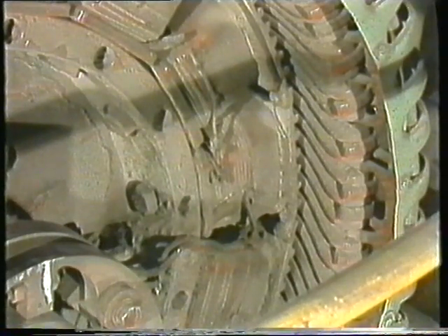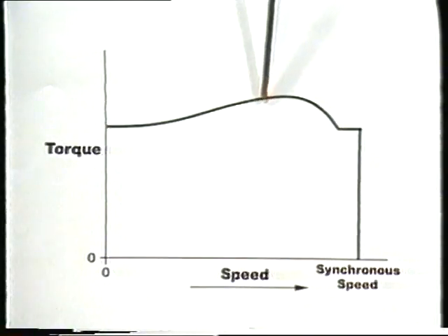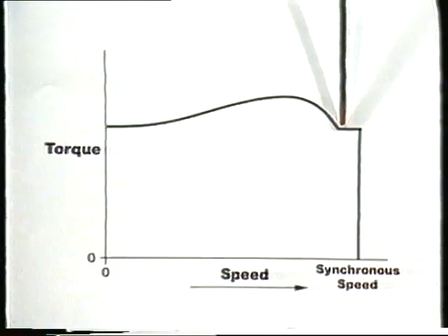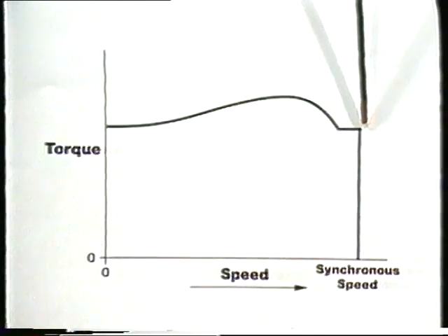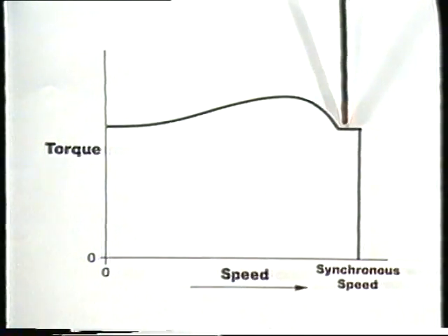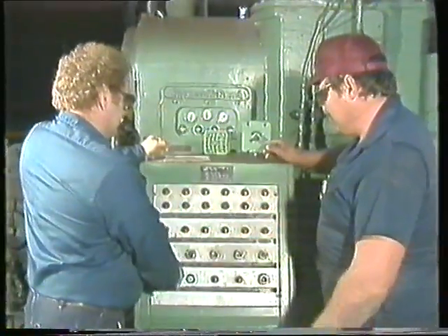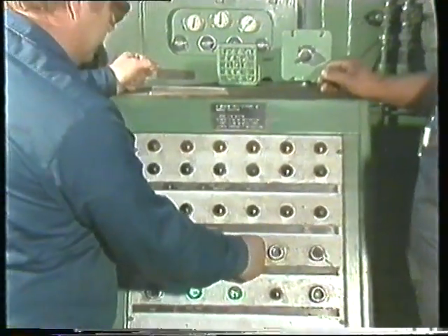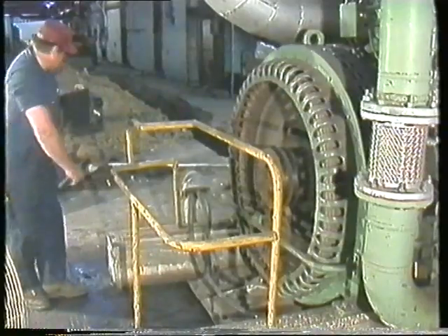Practically any synchronous motor you are likely to find will have a partial squirrel cage built into the rotor, however, which allows it to start and accelerate as an induction motor. When it is nearly up to synchronous speed, the rotor poles lock into the stator poles. If the motor ever drops out of synchronous speed, it becomes an induction motor again. But the cage is intended for starting only. The motor will draw high current and overheat if it does not pull into synchronous speed fairly quickly.